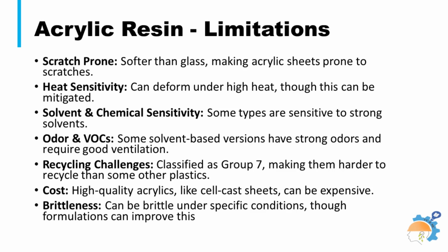Acrylic resins' limitations include poor heat and scratch resistance, brittleness, solvent sensitivity, potential yellowing from UV, and environmental concerns, making them prone to deformation and cracking, losing clarity and strength over time. These are difficult to recycle, especially impacting high-stress or outdoor uses despite their aesthetic appeal and versatility.